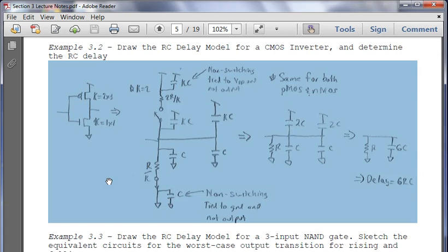And then all the circuits are going to have the ratio with respect to the input capacitance. So we're going to determine that the input capacitance for a 2-input NAND gate is 4. So we're going to use 4 over 3 as the ratio to help calculate, because everything is going to relate to the inverter calculations.